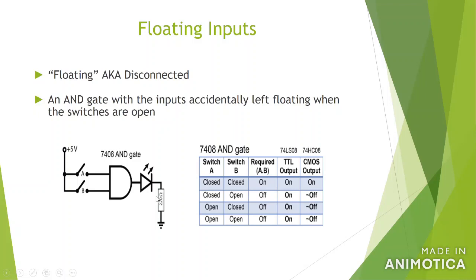And again, you have to have a resistor. If you don't have this resistor, you will burn this LED once you close the switch.